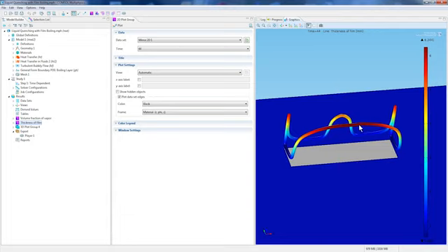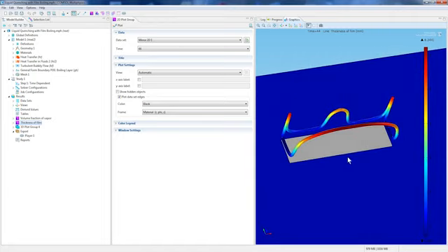Areas in dark red correspond to a thickness of about 6 millimeters, and areas in dark blue correspond to a thickness of less than 1 millimeter. As expected, at the bottom of the puck, the vapor is trapped underneath due to upward buoyancy force. So that's why we have a high thickness of the boiling layer here. The spikes here at the edges and in the middle of the top of the puck correspond to areas where relatively large amounts of gaseous bubbles are being introduced into the liquid.